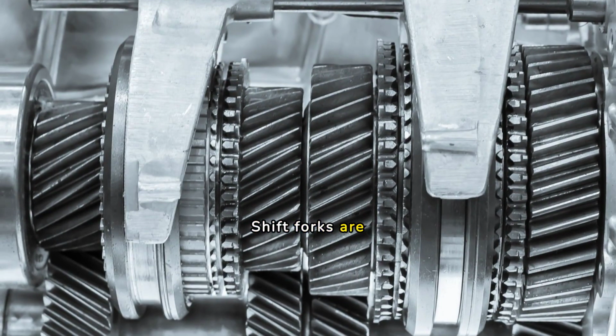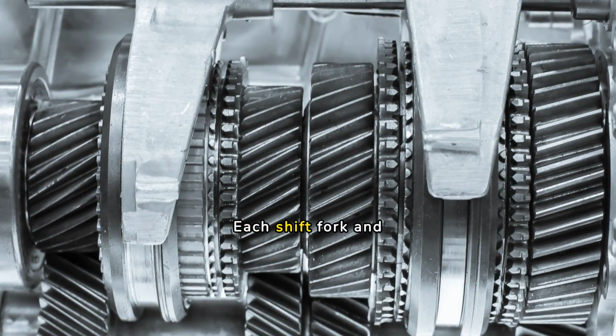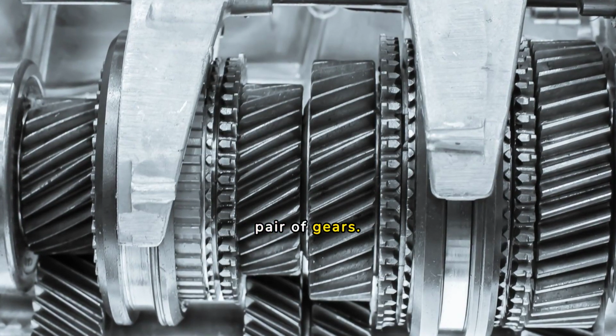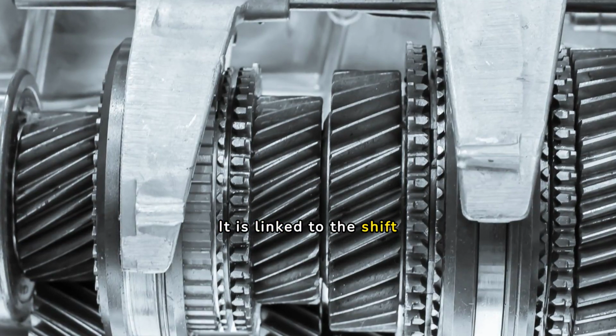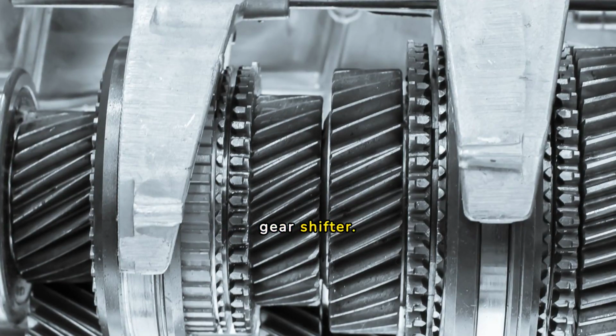Shift forks are connected to the synchronizers between gears. Each shift fork and synchronizer is used to engage or disengage a pair of gears. It moves the synchronizer back and forth between the gears. It is linked to the shift rod, which moves the shift fork when a driver uses the gear shifter.